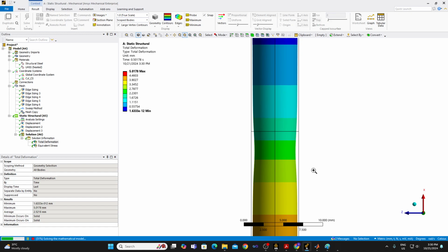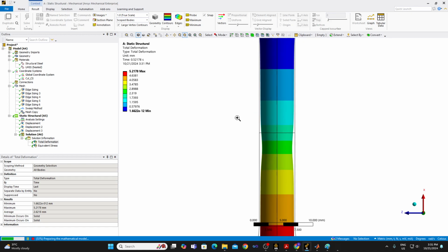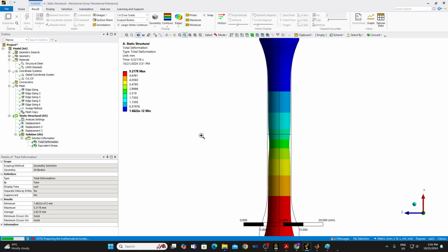Okay, and that neck is gradually becoming narrower and narrower, and because it's a simulation and we are using a material model that is suited for ductile materials, we'll have the perfect ductile material behavior, which means the neck actually contracts enough to touch itself, touch the other side of itself. Okay, so right now the deformation has been about 52%.